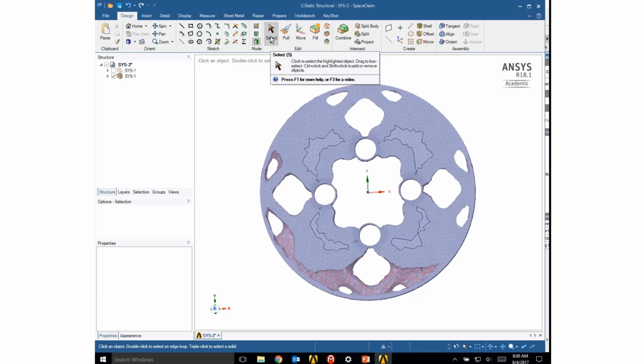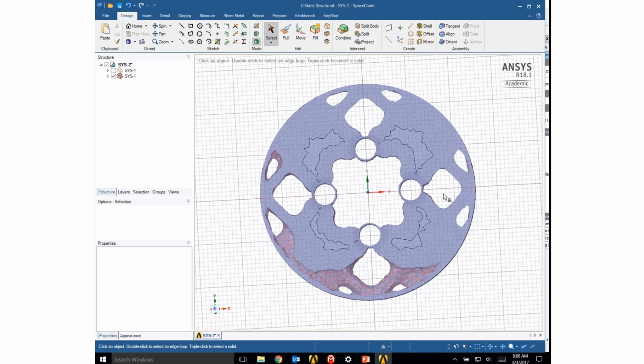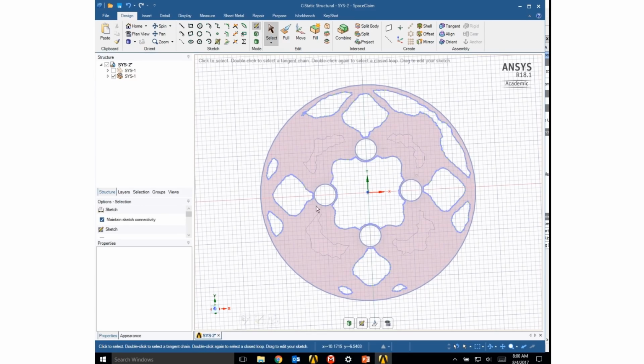So I go into the sketch plane and I want to look at this sketch plane, so I'll click there, now you can see all these lines have been made. And in many cases you'll be able to just smooth those lines and have a pretty good result. In this case that doesn't give us a very good result. And so I'm actually going to come in and delete all of these lines and use basic geometry.